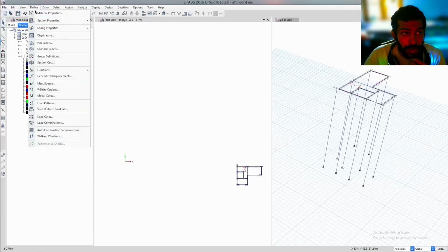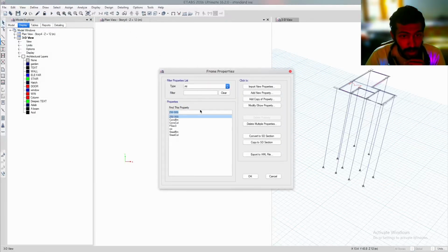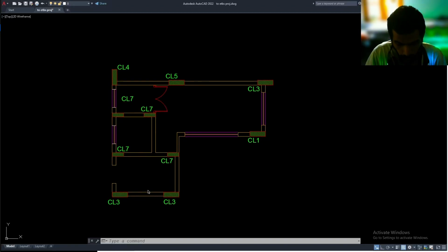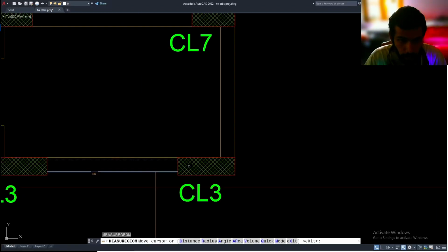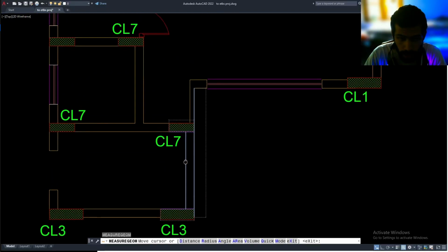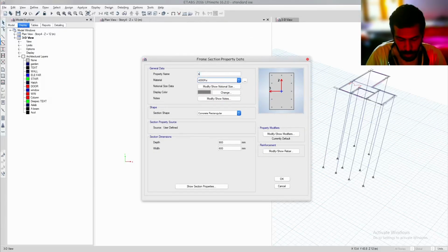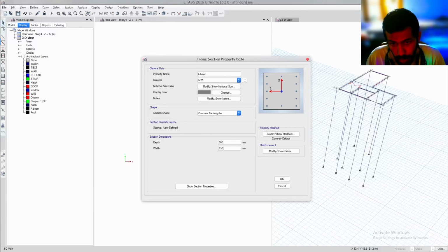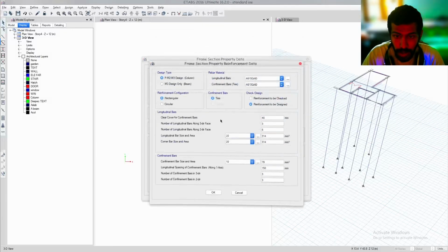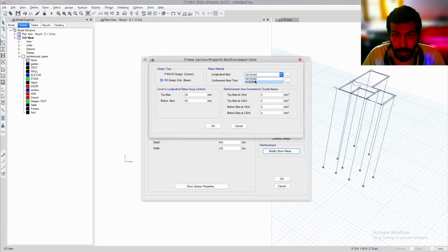Now for the column, first we need to define 2 sections. If you check this section and analyze the size, we have a wall of thickness 20, and here we have a wall of thickness 10. So add a rectangle, and this will be a major beam, B major, and can be an M25, and the size should be maybe 600 by 230. This is the size for a major beam, and I would like to change this option and understand the cover is always 20.